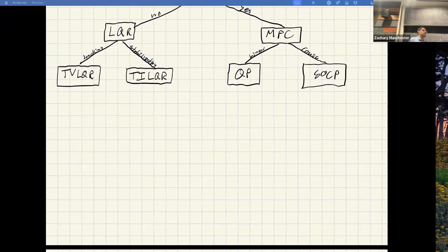In the case of bounded uncertainty in A and B, there's a very well-developed linear theory that was all developed in the 80s, basically, by people like John Doyle. It tells you, if you can bound those errors, here's a recipe for coming up with gains, K matrices, that are guaranteed to stay stable for any possible instantiation of those A's and B's within these bounds. So that's classical robust control theory.